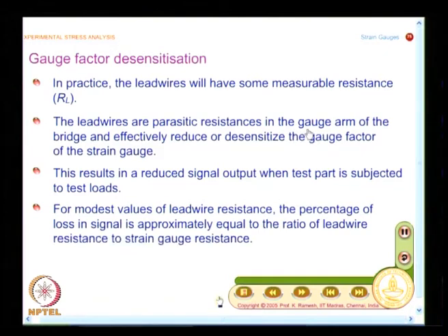You do not want them, you want to have a magic material which has no resistance and strain gauge is connected. See, I also said, if you have a magic material, a single speck of it can have 120 ohms or 350 ohms, I paste it at the point of interest and connect it and make measurement, then I have no problem about strain variation or gauge length influence, etc. And we saw it is just not possible. You need to have only a wire, and you need to have a minimum of 36 millimeter we saw, and you need to make it as a loop.